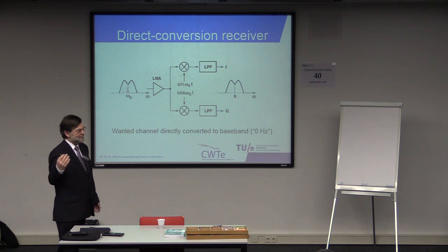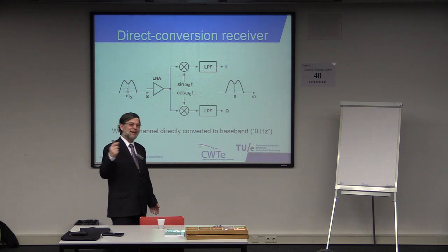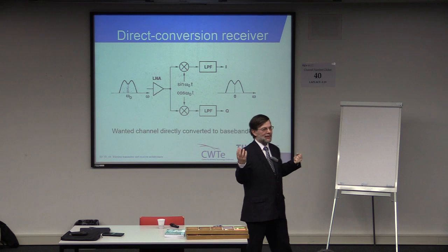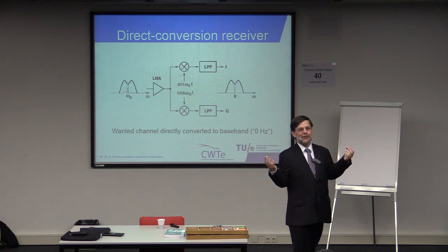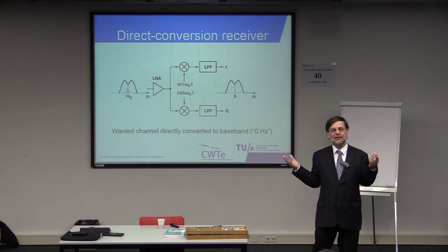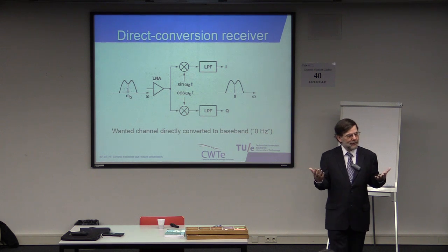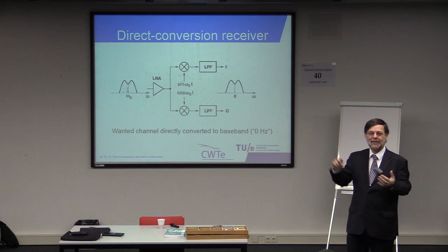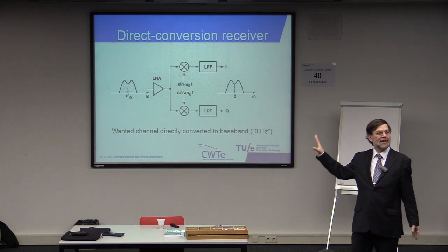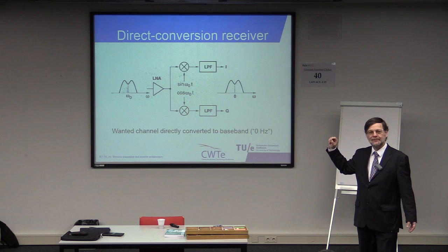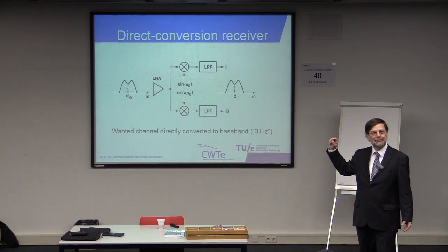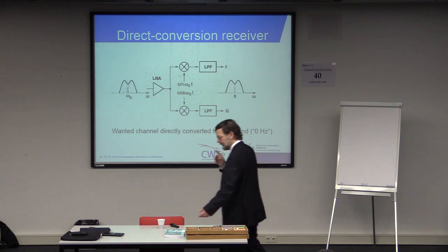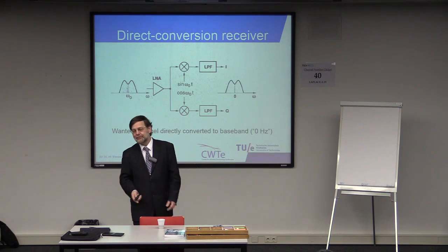So, great, right? You're back where we were. We're happy again. We're smiling because we have this concept of 0IF that seemed to solve all problems because I don't have an image anymore. Then we got into trouble because we could not distinguish positive and negative frequencies in my wanted signal. But we have a solution for that as well. So life is great and everybody does 0IF. Or not. There are still things.